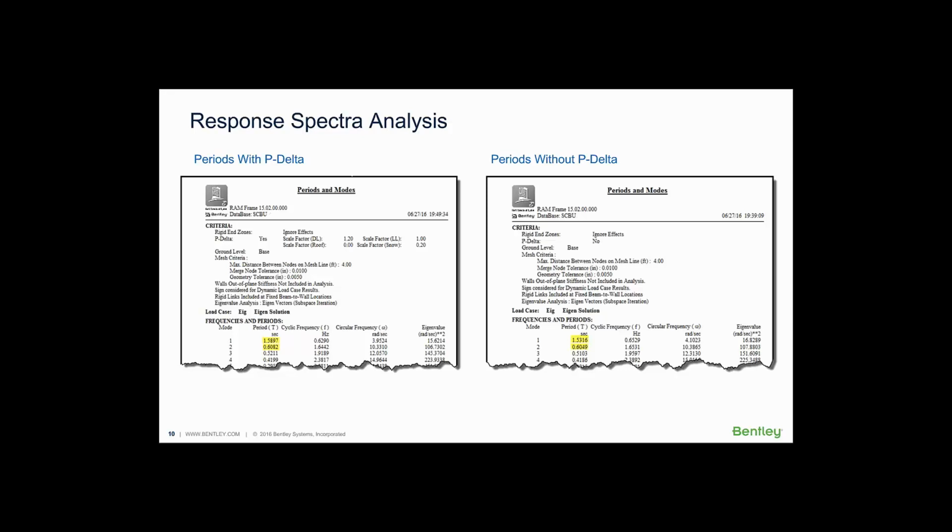Often that number is pretty small, 1.04, 1.05. If you have a particularly soft structure, then you can see some higher numbers. And if you start to see higher numbers, like 1.15 or 1.2, you might want to think about stiffening up your structure.